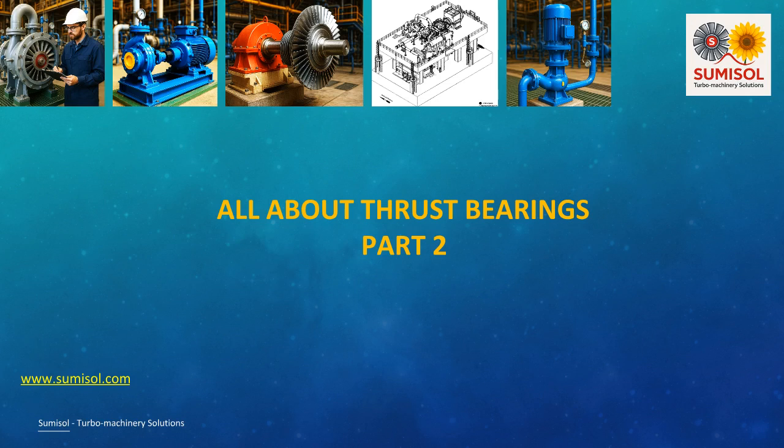The objectives of this presentation are to familiarize rotating machinery engineers involved in detailed engineering and site operation. Sensor mounting, methods of proper setting of thrust bearing end play and voting are also discussed as a part of on-site work carried out during pre-commissioning activity of mission-critical turbomachinery. The first part had explained types of thrust bearings. The second part shall explain thrust positioning of rotor, installations and setting alarm and trip.